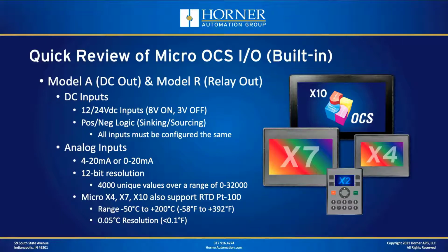On the analog side of things, basically you have your choice between 4 to 20 milliamp input range or 0 to 20 milliamp input range. And you've got a resolution of 12 bits.